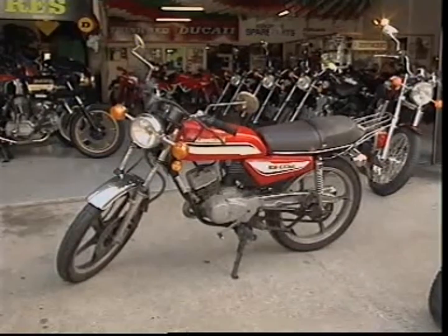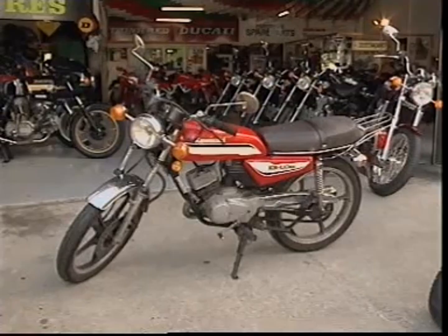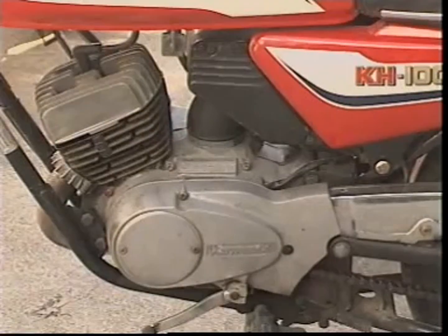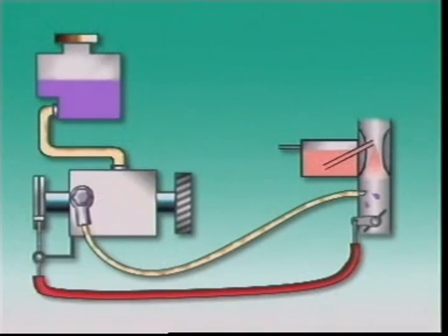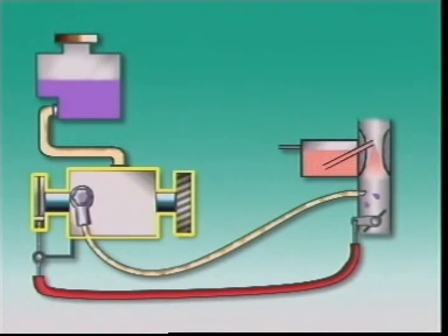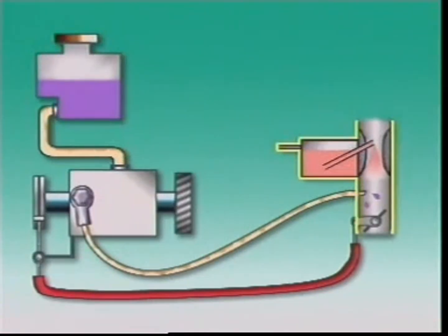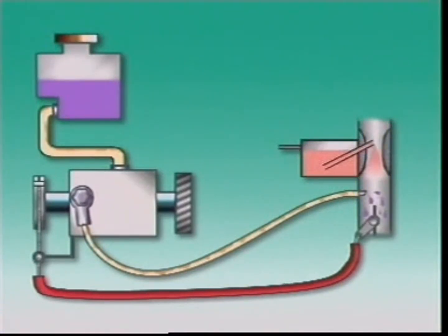Some two-stroke petrol engines use an oil injection system. This system doesn't need the oil and petrol mixed manually. An engine-driven oil pump takes oil from a tank and pumps a measured amount directly into the engine, where it will mix with the fuel and lubricate the internal engine parts. The pump delivers the correct amount of oil for the engine speed and the throttle setting, which makes it a more precise system than running the engine on a fixed oil-petrol mixture.